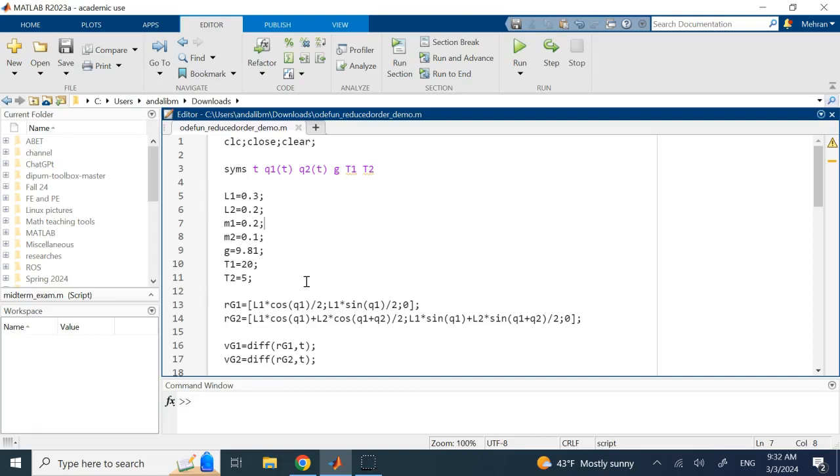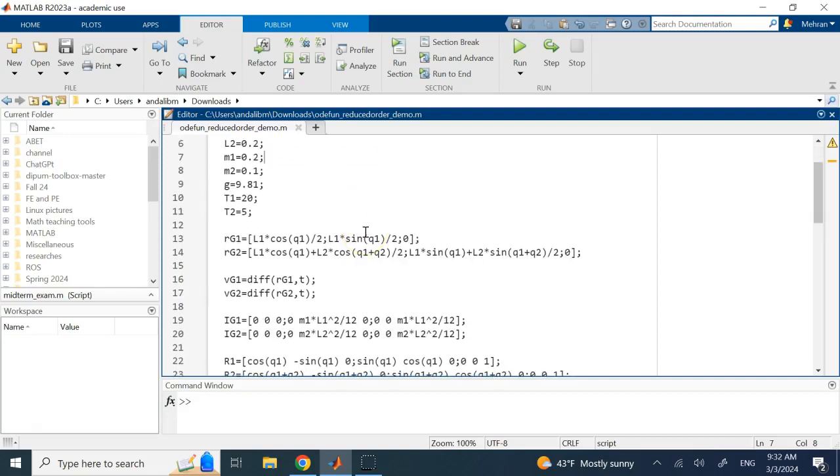Because if you don't, when you get those symbolic equations, you have to manually assign some variables and then rewrite everything in terms of those dummy variables to write your ODE function, right? To write that function that you always pass to ODE45 or anything, so you can use it. So can everything be basically automated so you don't need to do any manual work, all done in MATLAB automatically?